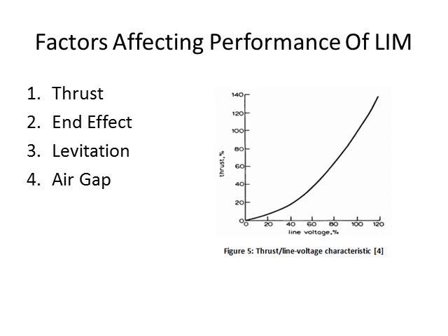The third factor is the levitation, which refers to the presence of an air gap due to an electrodynamic levitation force. This occurs in single-sided motors and does not occur when an iron-backed plate is used as the secondary, since the resultant attraction overwhelms the lifting force.